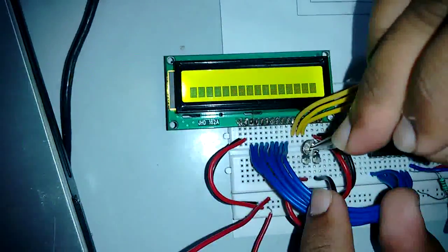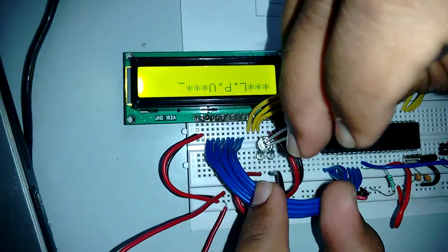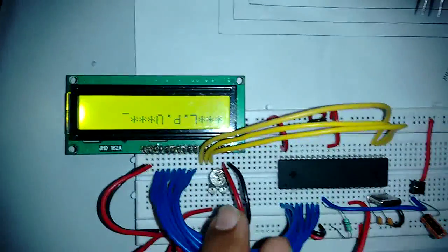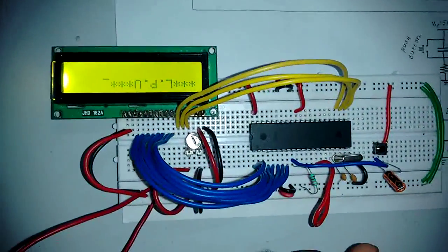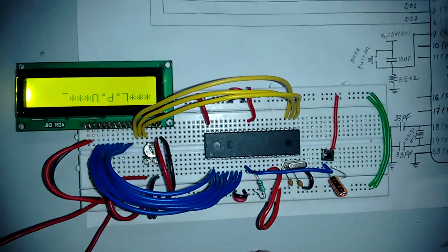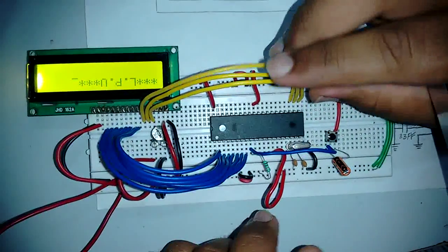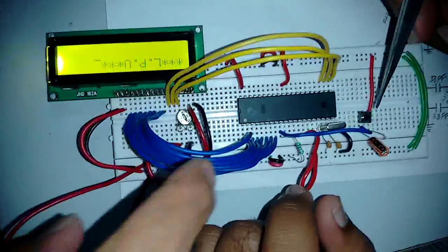And one troubleshooting step you require: if your LCD is not displaying the characters, first check the control pins and then check the data lines of your LCD. Then take out the crystal oscillator and reconnect it with the capacitors. And one more thing is the capacitor of your reset switch, which is to be reconnected again. Fine.